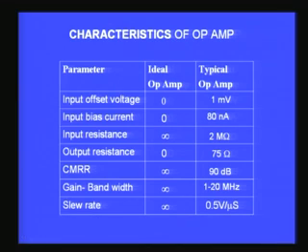It cannot be 0 because the input terminals correspond to the terminals of the base of the two transistors which form the differential amplifier configuration. And therefore, the amplifier, if you want it to work like an amplifier, should have some minimum, though finite, current flowing through the base terminals of the transistors. Therefore, it is impossible to have a 0 bias current, even though we list it as 0 in the ideal case.